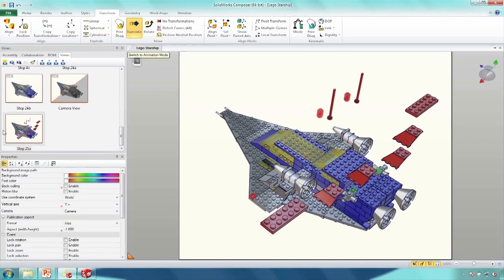If I right click and say copy and right click paste, that's another way in which you can create a view. Just F2, change that to 25B. And remember, anything between A and B, in B it's restoring it to its neutral position and then the color as well. Now, the easiest way to do that, remember, it's not restore neutral position, but it's actually restore neutral properties.